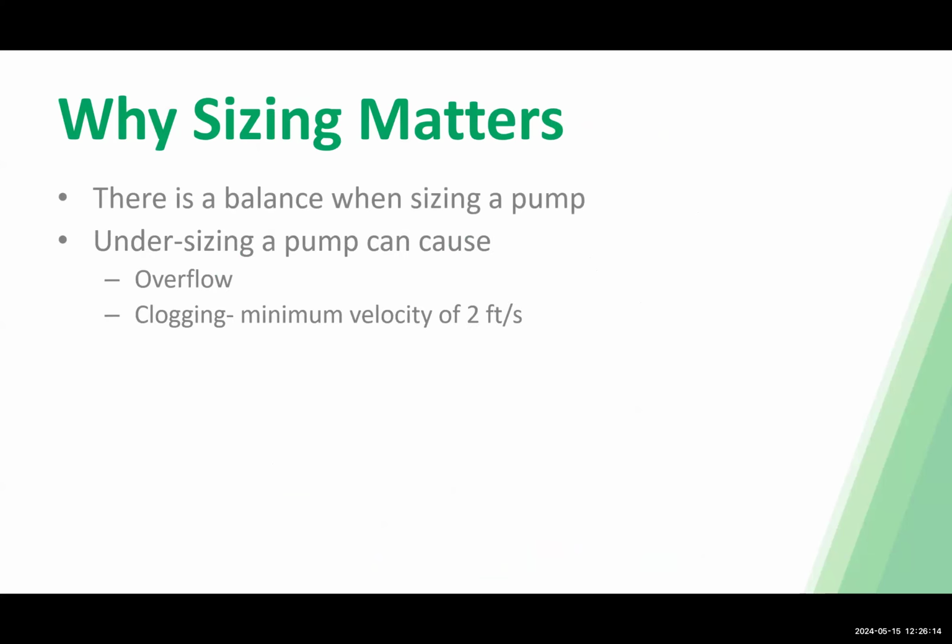Undersizing a pump can cause a few issues, such as overflow. If your pump cannot keep up with the liquid or the wastewater that is coming into the basin, wherever that pump is located, you're eventually going to have overflow issues with it, and you're going to have to replace the pump with something that can handle those flows that are coming in.